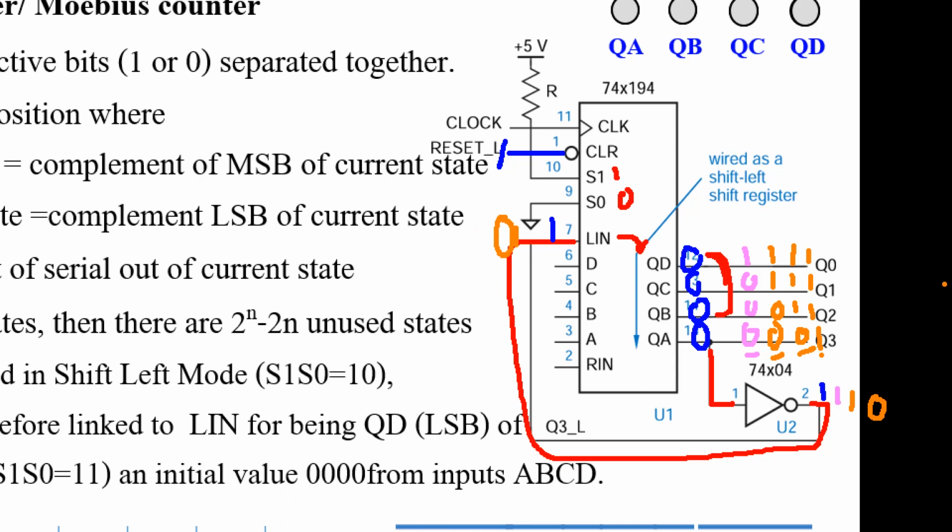That means now in is 0. When the clock ticks, copy these 3 bits, okay, 1, 1, 1, and in is 0, right? Then shift to here. Now this is 1, so now in is 0. When the clock ticks, copy these 3 bits 0, 1, 1, and read from in, which is 0.